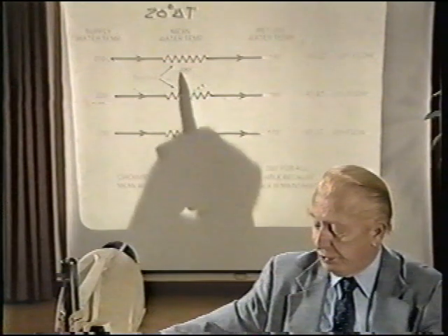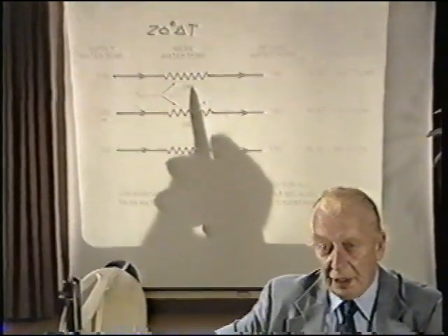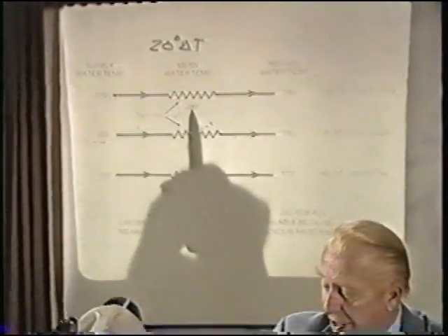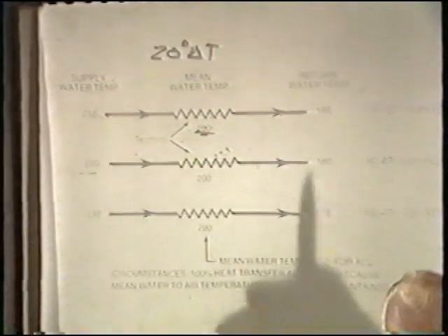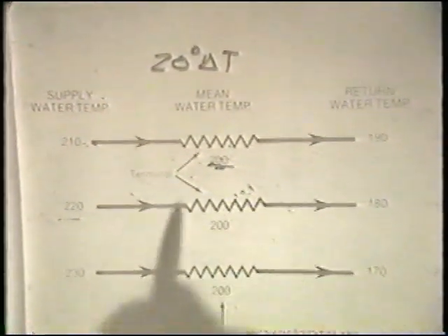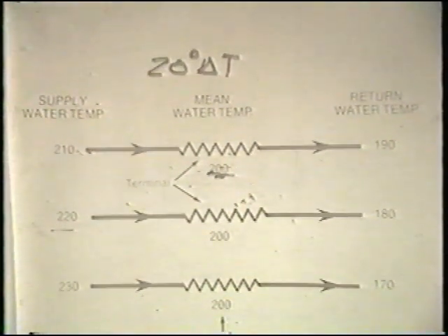In terms of the baseboard terminal units, so long as we provide a consistent mean water temperature through the terminal units, we will establish the same heat transfer capability.